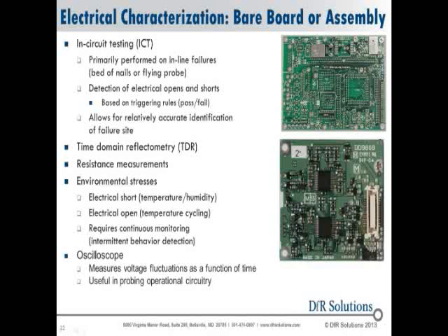And again, if you're not finding anything, adding in some environmental stresses, temperature and humidity, temperature cycling, vibration and shock, just a few good raps every now and then might bring an issue to fruition for you that was there, disappeared, and you're trying to bring it back again. So you can find it and do something about it.